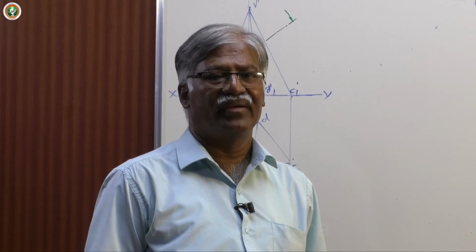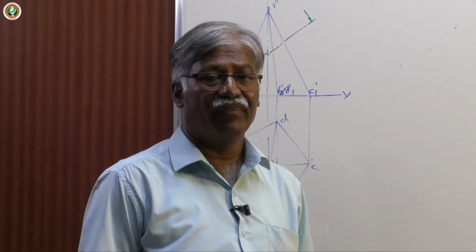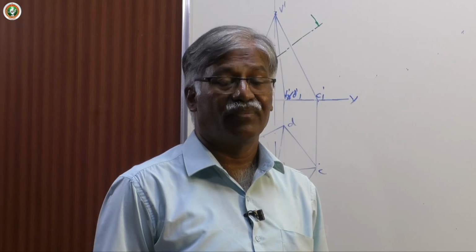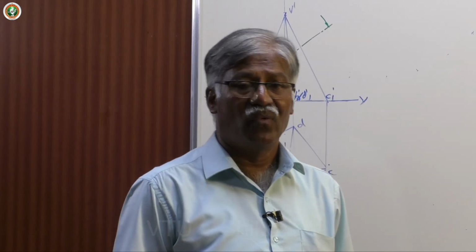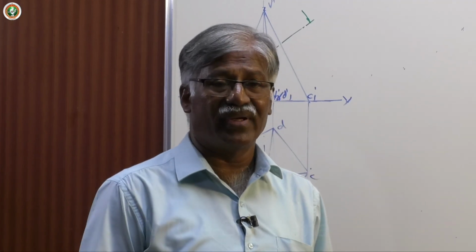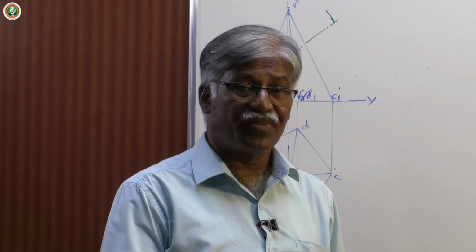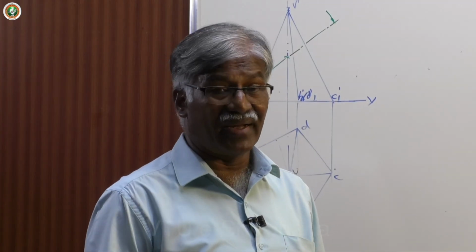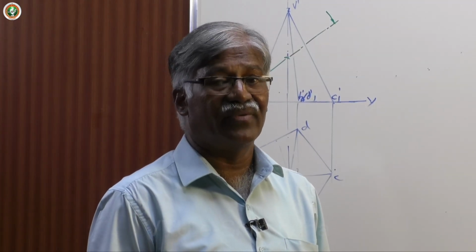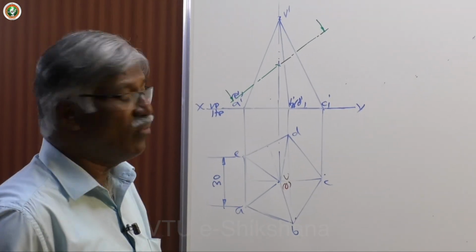Today let me take the very critical, it is simple but it is very critical, pentagonal solids, particularly pentagonal pyramids, wherein the true length plays the main role. In all cases true length plays the main role, but here identification of true lengths of corresponding distances, particularly in truncated solids, is very important. Now let me take 2 to 3 problems and discuss.